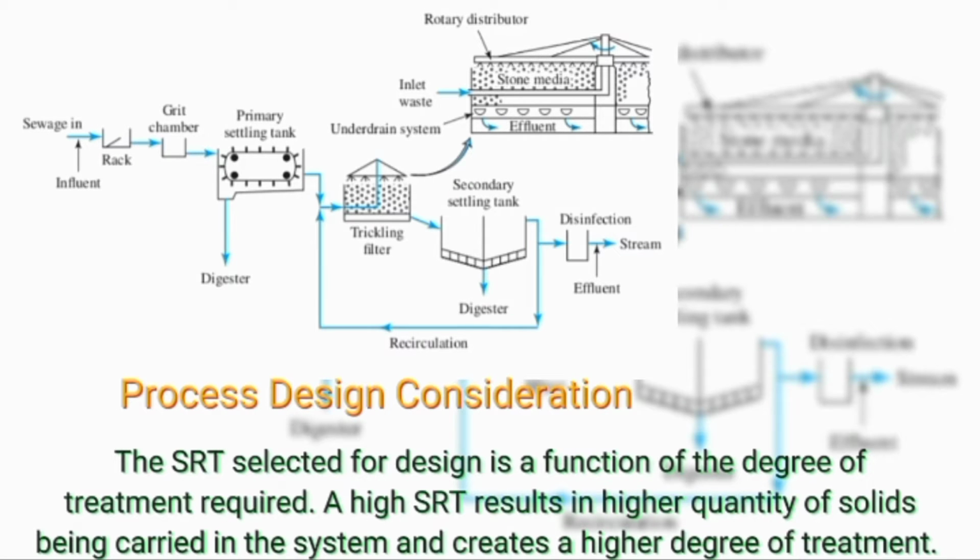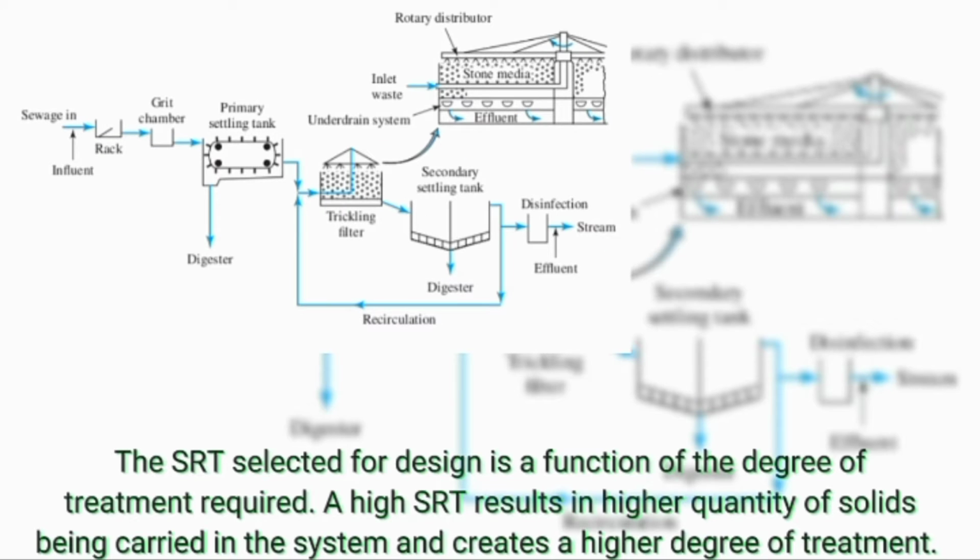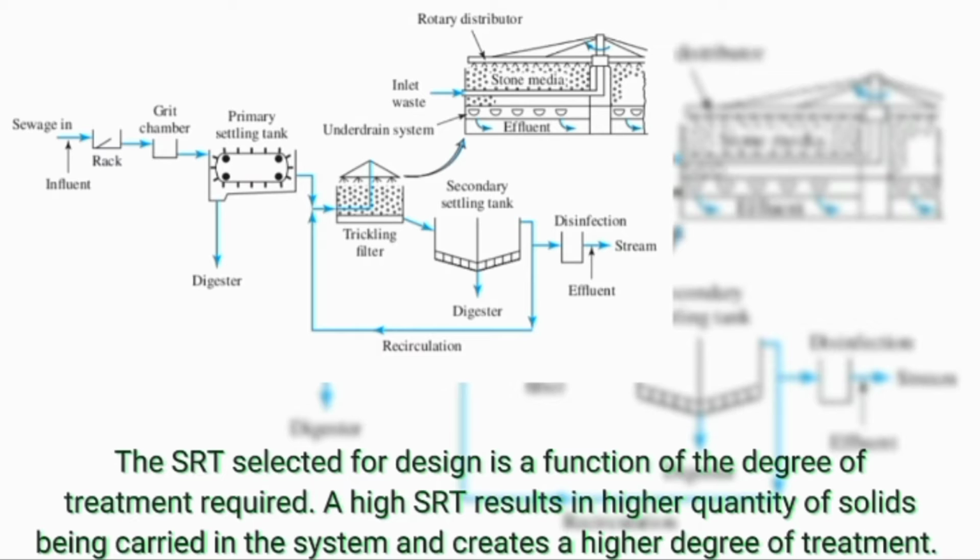Process design consideration. The SRT selected for design is a function of the degree of treatment required. A higher SRT results in a higher quantity of solids being carried in the system and creates a higher degree of treatment.